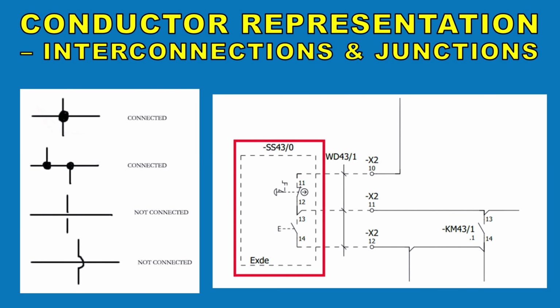Interconnections within wiring diagrams are represented by conductive paths. Solid lines denote continuous conductors, while dashed lines indicate optional or hidden wiring paths. Junctions where conductors intersect are marked with connection nodes, whereas non-connected crossovers are depicted without nodes to prevent misinterpretation.